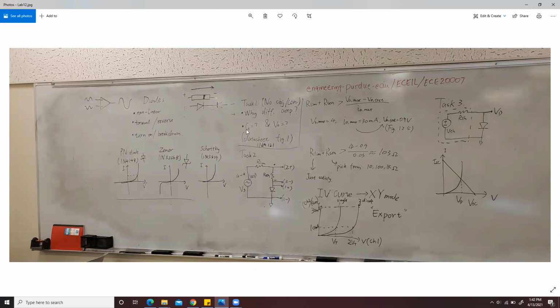That's why in the previous semester, when we did this lab, you needed a differential op amp to transfer the differential signal to a single-ended signal, so that the benchtop oscilloscope could read the signal. But this semester, since you are using AD2, AD2 can directly read the differential signal. So actually you don't need the differential op amp in here.